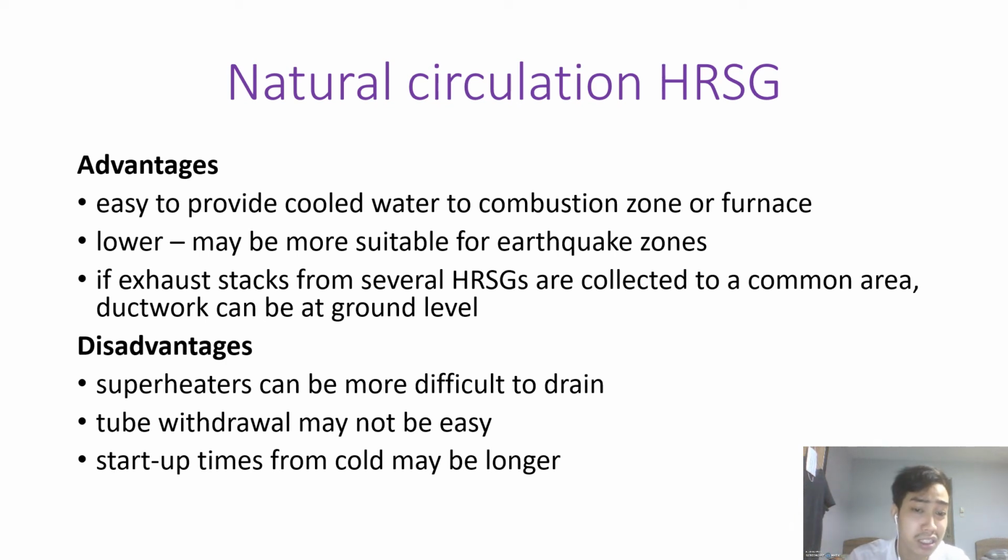Moving on to the disadvantages. Firstly, superheaters can be more difficult to drain, and tube withdrawal may not be easy, making maintenance work fairly difficult because of the tight space, and also startup times from cold may be longer.